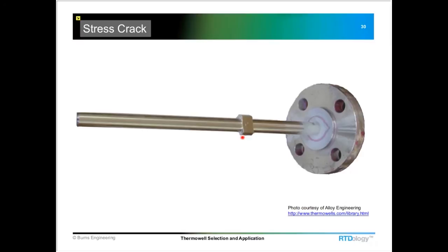But the new version of the wake frequency equations and calculations do not allow a velocity collar, and the reason for that is that they don't really ever fit up tight enough in whatever they're inserting into, and the well can still vibrate in there, so they really don't account for those anymore.